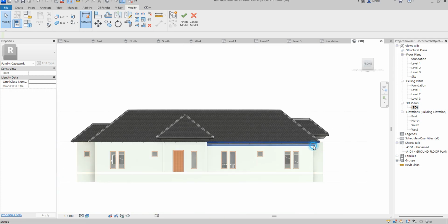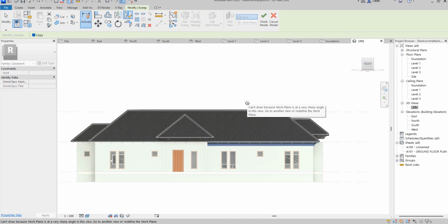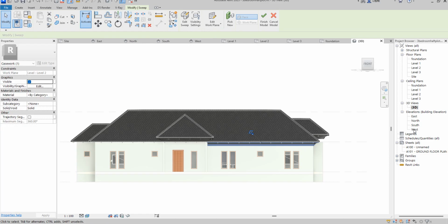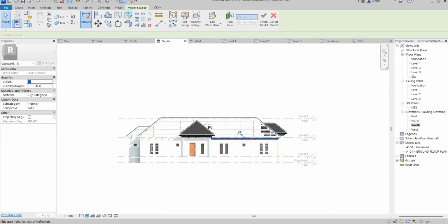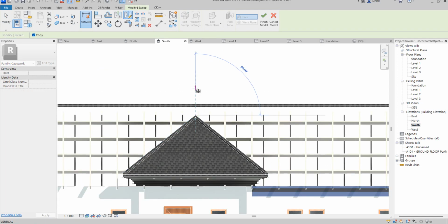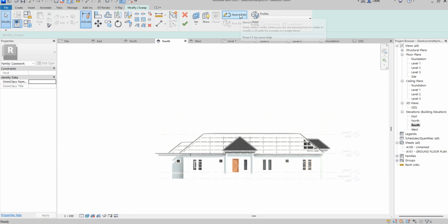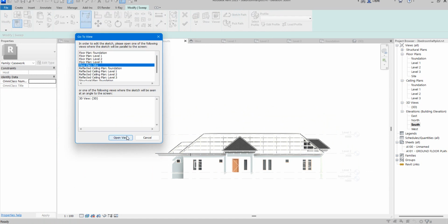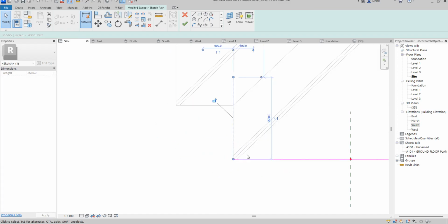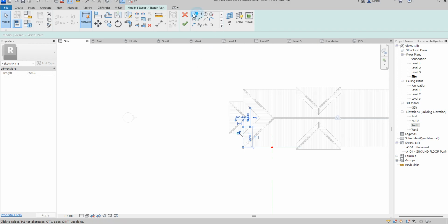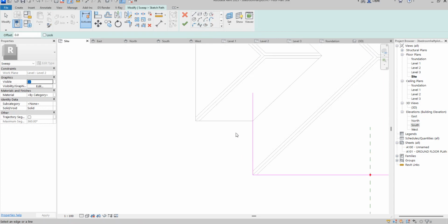So what you do here now is that you mirror this. You just need to mirror only that side. Sorry, you're supposed not to do it on 3D. So you go to south elevation. Yes, from this south you click and you say mirror. So you see this one to mirror it. So it's fixed. Then you need to edit that. Then go to sketch, work on this side and open it completely. Now you can fix everything in order, but this one goes around because they are of the same level. So you select that and let me use the fit line.